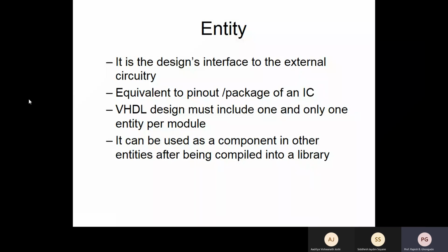One and only one entity. So a VHDL design, whatever design you have, will have only one entity. Please remember that. This entity also can be used as a component in other entities, but of course after being compiled into the library.